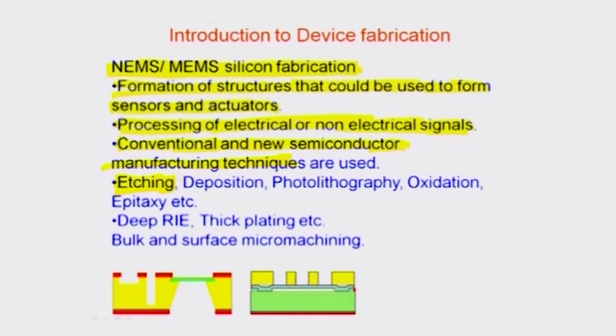It could be deposition, where you can deposit a metal film or a resist film on the top of some of these wafers. And then of course photolithography, where you can use the power of optical signals or light to actually carve and find out different features, sizes and structures onto these films.